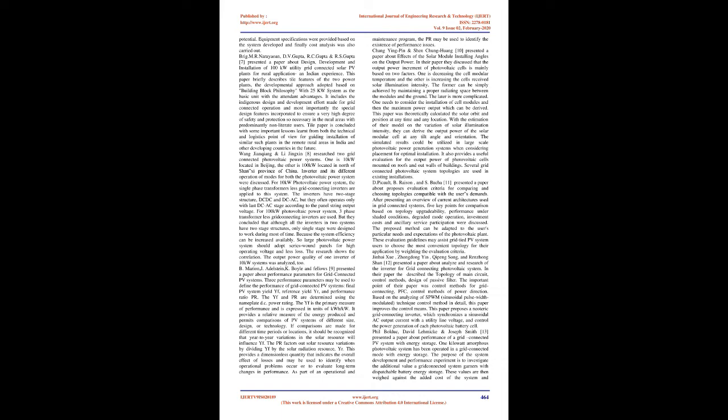1.2 Problem description. A simulation model of a general photovoltaic module is to be constructed in Simulink. The inputs to the model should be solar irradiance and ambient temperature. It must be able to operate at the maximum power point to compare the output to measured values with the help of an MPPT controller with the Perturb and Observe algorithm. The battery system with the voltage source inverter is to be fed to the AC grid, and energy management for the power flow must be done as per the requirement of the system.